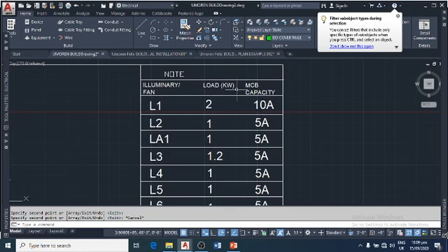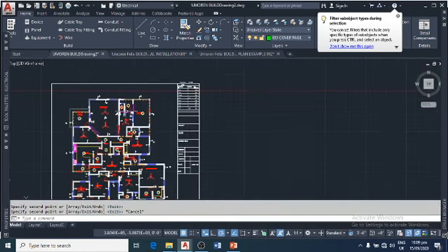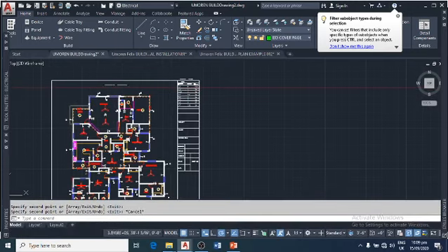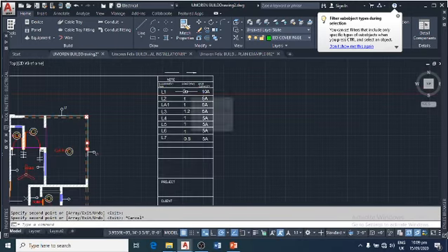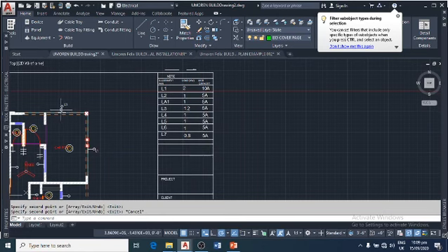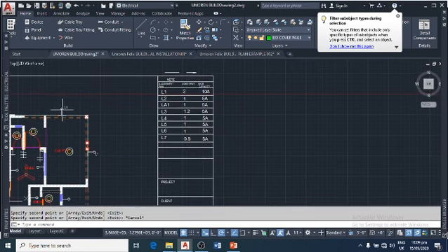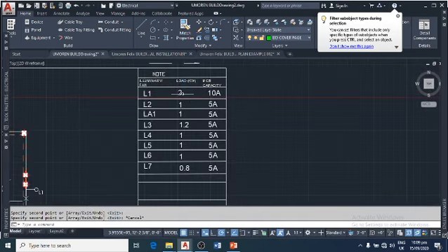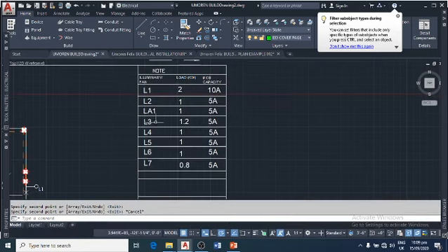This implies that the total load we are using for this particular building is about 2 kilowatts. So maybe we are using bulbs of up to 100 watts at each point, so we are calculating up to 2 kilowatts. Now selecting our MCB, that is the miniature circuit breaker, for each of these, 2 kilowatts divided by the supply voltage.